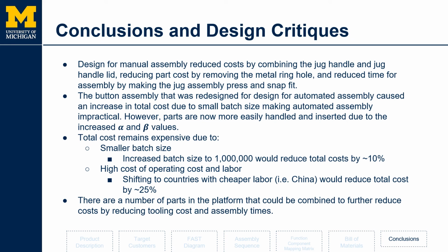All right, so some conclusions and design critiques. So for the design for manual assembly, the jug assembly, we were able to reduce the price by a significant amount. We removed a lot of unnecessary features, we combined a lot of parts, and we were able to introduce snap fit instead of small screws.